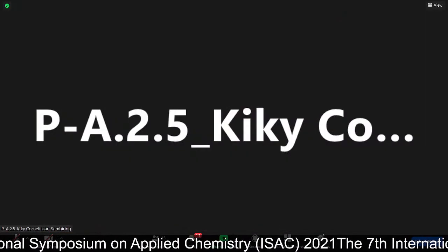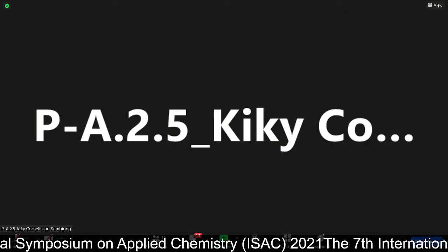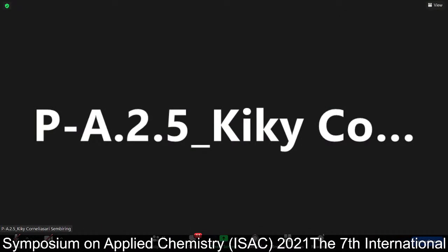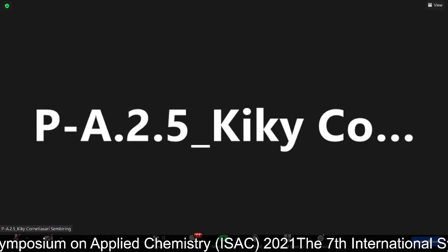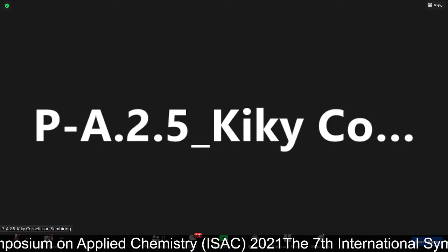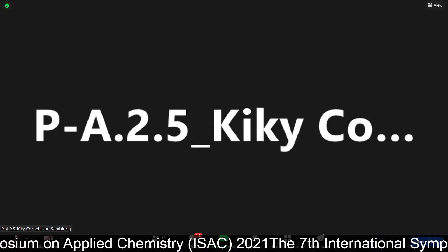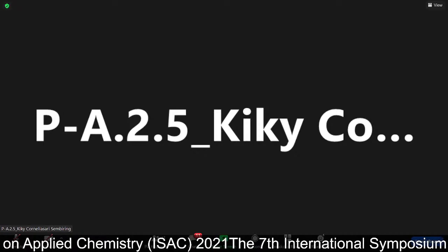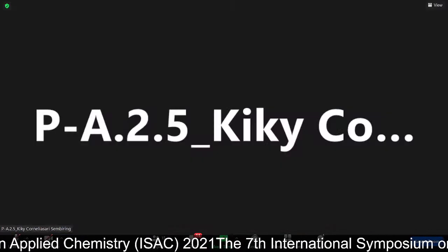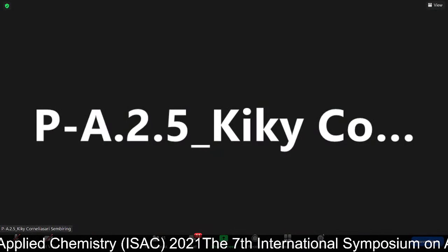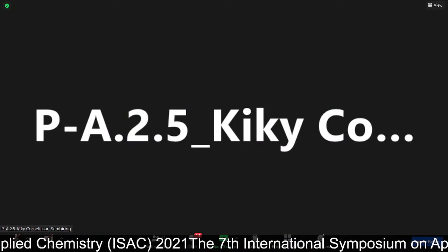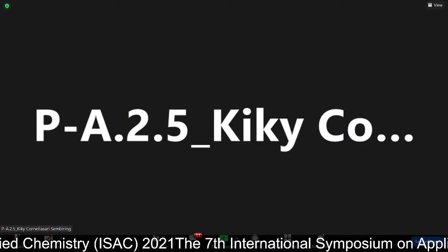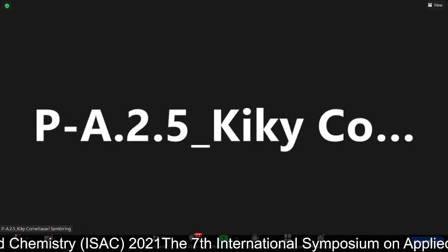In the production of green diesel, we use fatty acid, and the fatty acid is produced by palm oil hydrolysis, because if we can separate the saturated and unsaturated, the catalyst will selectively run for the saturated fatty acid only, not the unsaturated fatty acid.